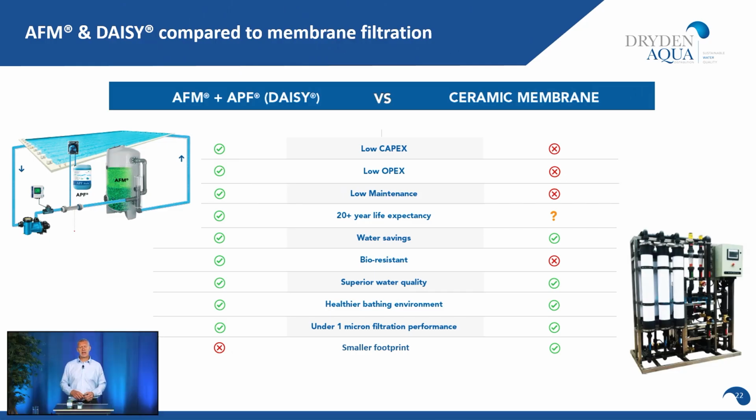AFM, as I've already mentioned, is 100% bioresistant. We can't say the same for ceramic membranes. They are subject to biofouling and do need to be cleaned on a regular basis with cleaning solutions. However, the water quality for both systems is very, very good. Healthier bathing environments, yeah, this is because we're not producing such toxic chlorine byproducts. We've given the ceramic membrane a tick there, but if the system were to become biofouled, then you would get an increase in such byproducts.